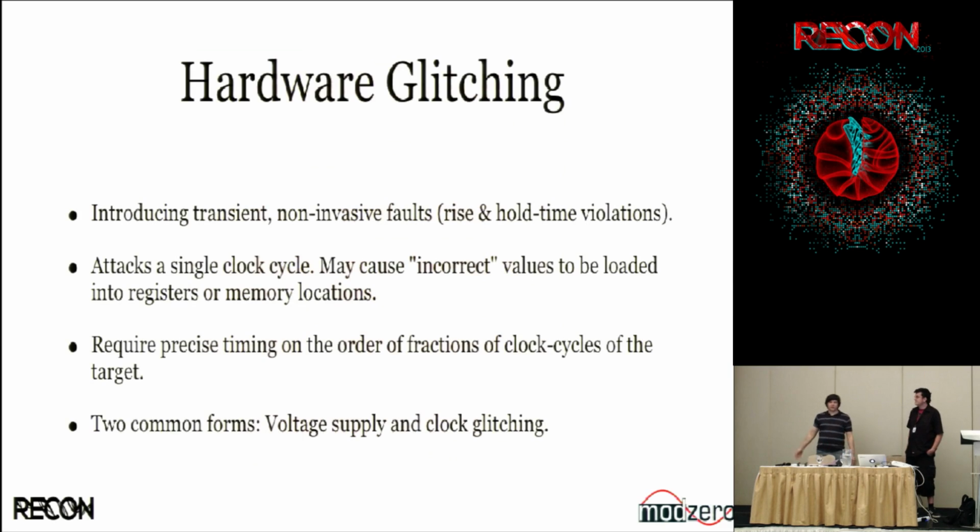So another one that I'm going to talk about, but Olivier will also talk about it more tomorrow. So make sure to come to Olivier's talk tomorrow. It is basically hardware glitching. Hardware glitching means we somehow introduce some transient faults to the execution of the system. We play around, for example, with the voltage or the clock. Those are the 2 main types of glitching. There are crazier ones like laser glitching, which we might get to see tomorrow. But all of these things work on embedded devices.